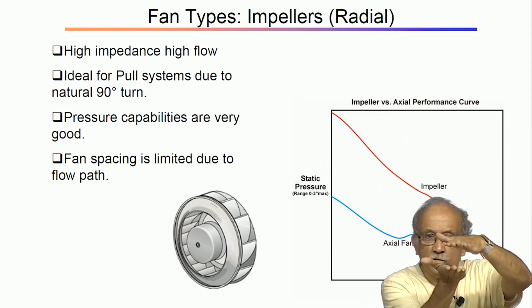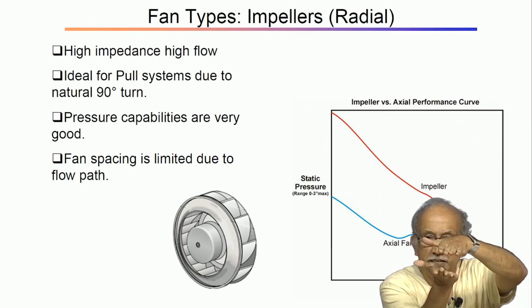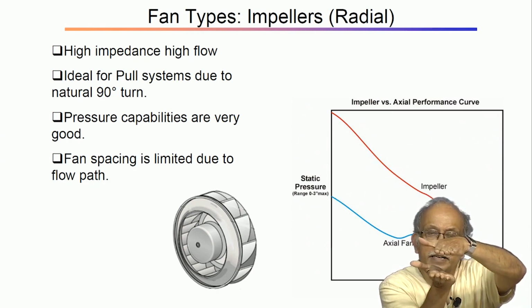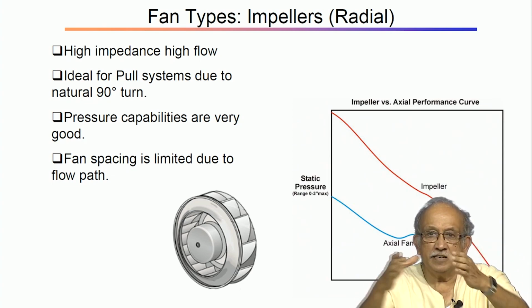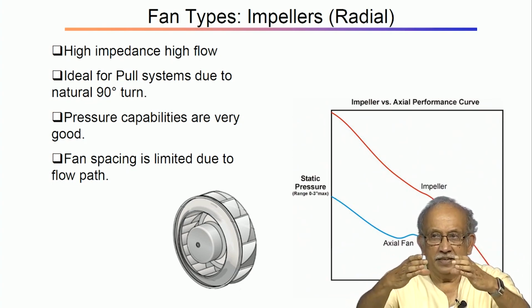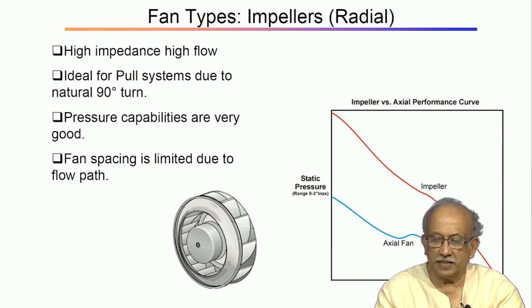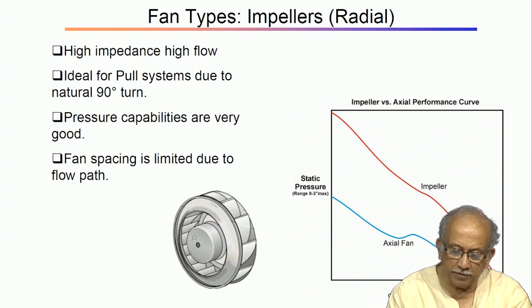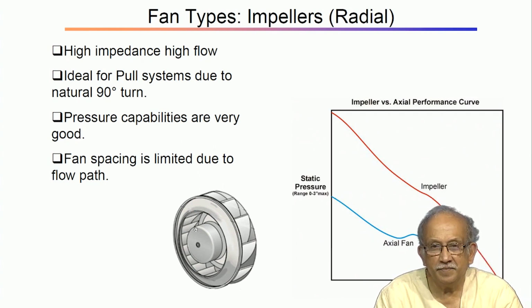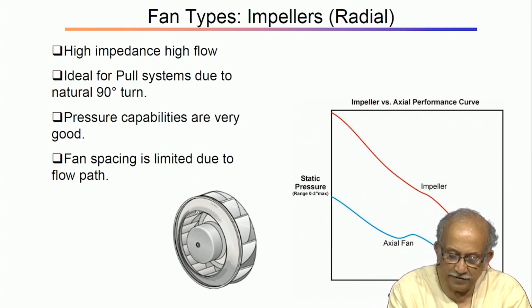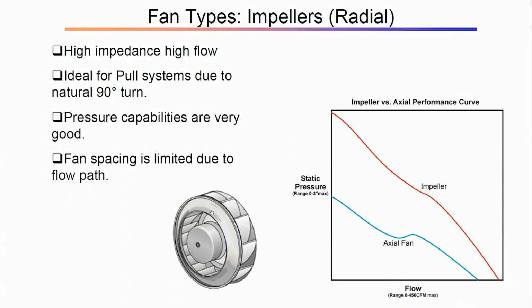But this is very low. If you see a fan like this, typically they are only about 80 mm. You have about 100 mm also, and then width starting from 250 mm, then 300 mm. So, you have 300 mm by 80 mm, beautiful circulators are available, and you see here it probably has a built-in motor inside, and the pictures also show the rotation. In this case, the vanes seem to be curved backwards. I will stop it here.